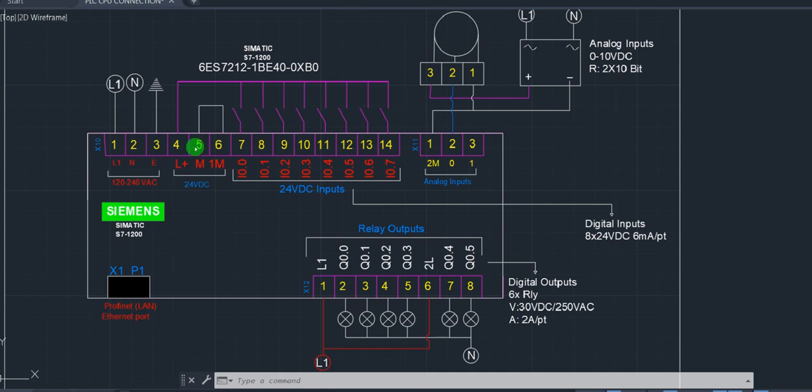For example, here I have my live supplying all my input bits, all my switches. This is live. In that case, on my output, my neutral is going to come to the lamp for the circuit to be complete. If I use my live conductor here and also my live conductor here, you will not have electricity flow because you don't have a closed loop. Neutral is here, live is here, and both of them will conduct through the CPU communication.